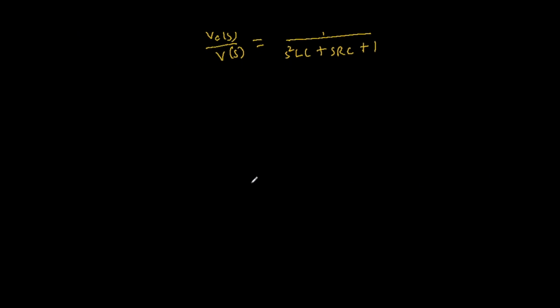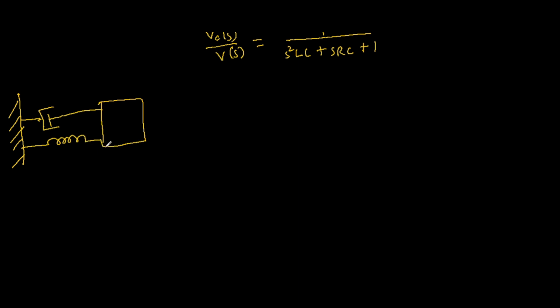Let's pick a different system. Let's say we had a rigid wall here on the left, and a mass tethered to the wall via a damper, and let's also include a spring in here. I have friction on the ground, but that's fine. And then let's apply a force f(t) over here. This is a mass, I'll call this D and I'll call this K. Based on this system, we're assuming displacement is towards the right, so we can just call this x(t). We don't need to put the 1 since there's only one displacement.